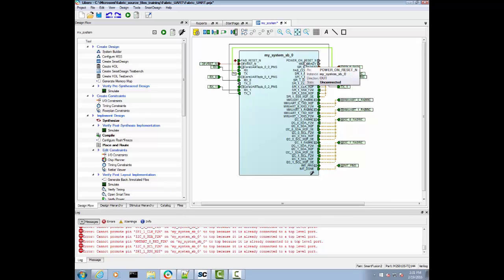The idea here is that when you first boot up the SmartFusion2 device, the Cortex runs some boot code. It writes registers for things like the DDR controllers if you're using it, or the SerDes blocks. So it's not instant on like the Fabric is, because the Fabric has a flash interconnect and it's non-volatile. And when you turn on the power, the Fabric's ready to go. The Cortex takes a little bit of time.